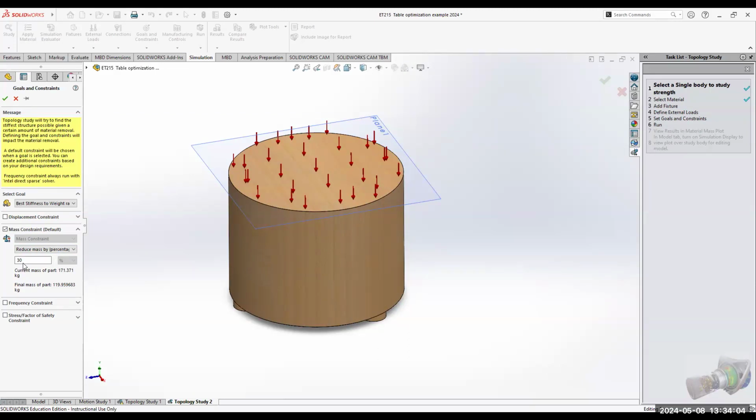For a 30% reduction, I feel like that's more like 30% left over. So yeah, I think that might be what it's doing: if you say 30%, we're keeping 30%, and that 70% is reduced. That could be why this shape is taking so long to optimize, because we're removing so much. So you could build a bulky shape that's closer to what you want and then optimize that, and it would have to remove less material. Does that make sense? Mhm.